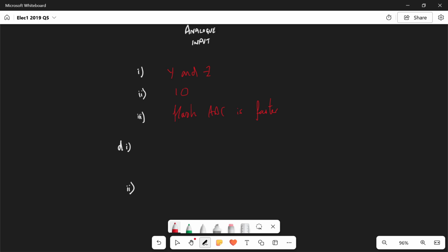Okay, D part 1. A microcontroller is configured to have a 9-bit input port. An 8-bit ADC is connected to the input port of the microcontroller. How many op-amps would the modified circuit need to include overload indication? And that is where output P comes in. So output P has its own op-amp, and we need to bear that in mind.